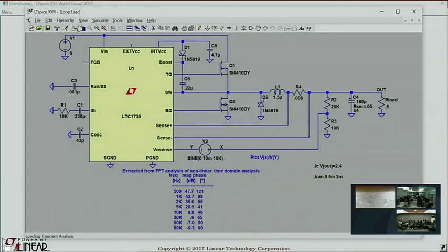Well, it turns out that when you got the design review meeting to agree to only discuss frequencies well below the switching frequency, because you couldn't analyze the nonlinear part of the circuit, so it's the only thing you could analyze, that's not nearly enough. If you actually analyze the circuit correctly, that is in the time domain with all the nonlinear stuff, then it turns out you have to roll off the transfer function well below the Nyquist frequency, not well below the switching frequency. That's a very low frequency indeed. That delay is negligible. That means this feedback loop is two poles and two zeros, and that means it's stable.